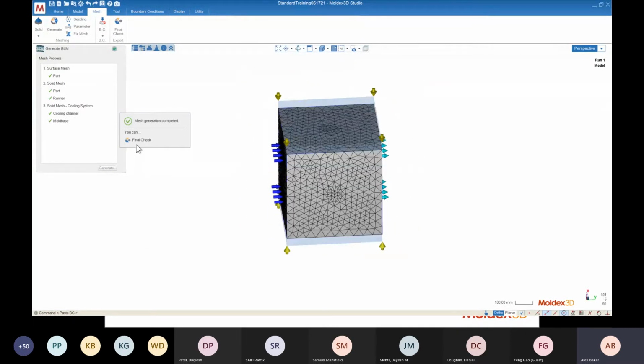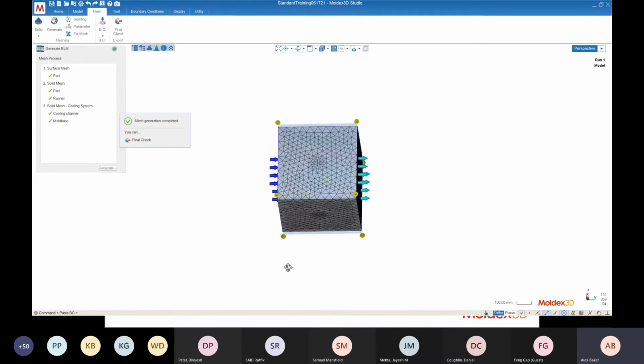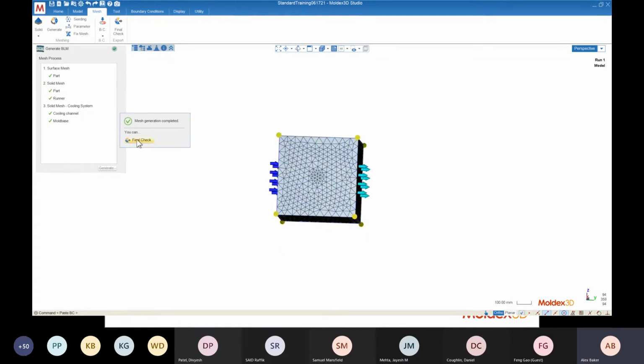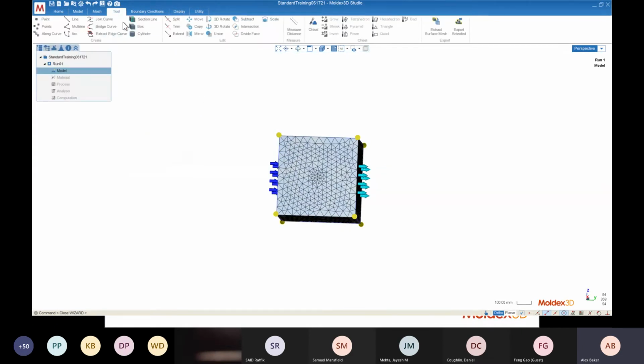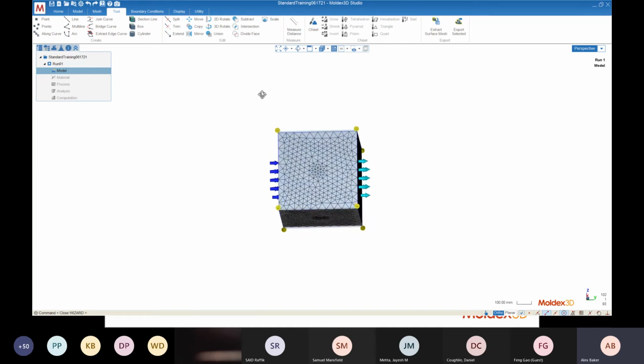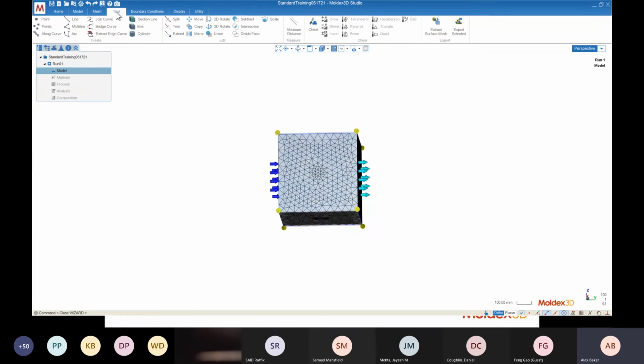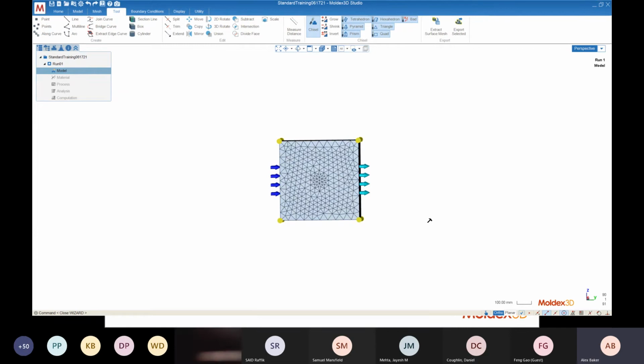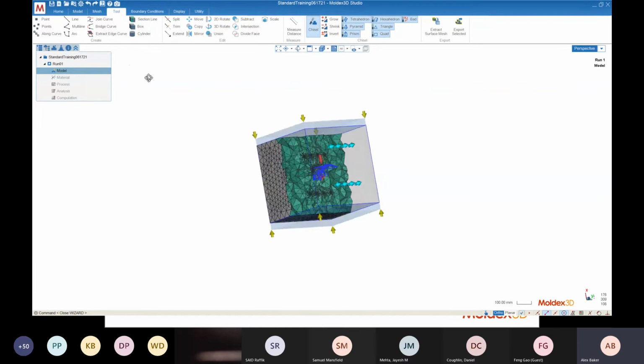And before we export our mold, you can go ahead and click Final Check and just follow along with me visually here. Or if you'd like to, you can also chisel the model along with me. So to chisel, we're going to go over to the Tool tab. And over towards the right, we're going to click Chisel. And then we're going to left-click drag a box. And any element contained within that box is going to be temporarily hidden.